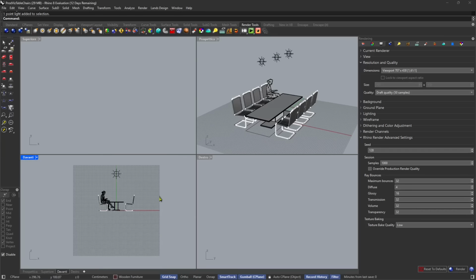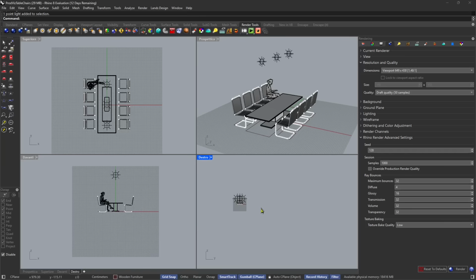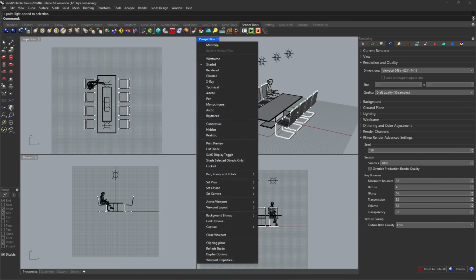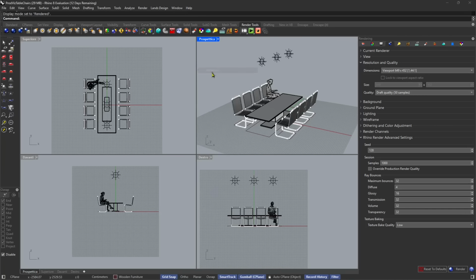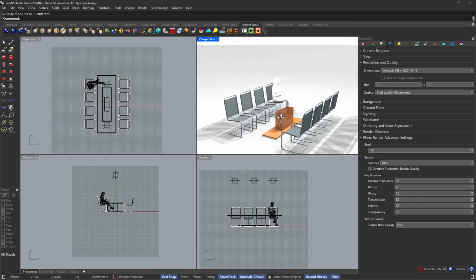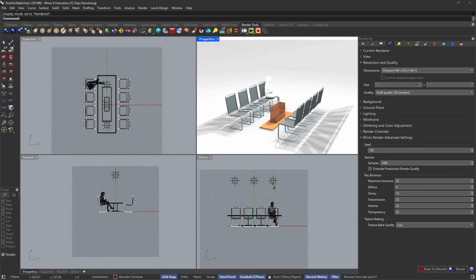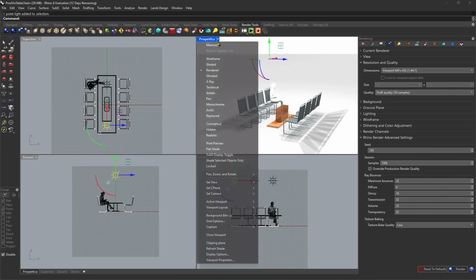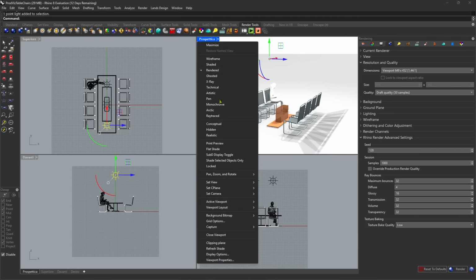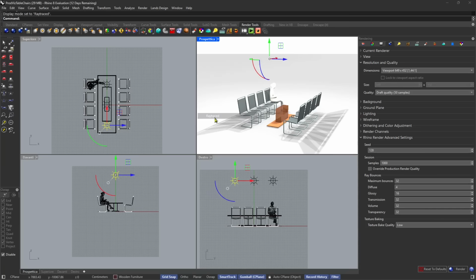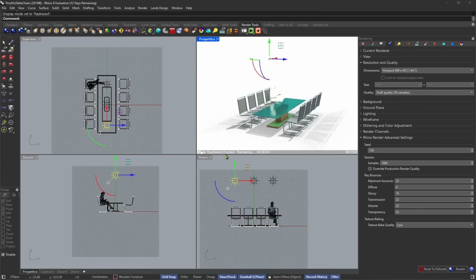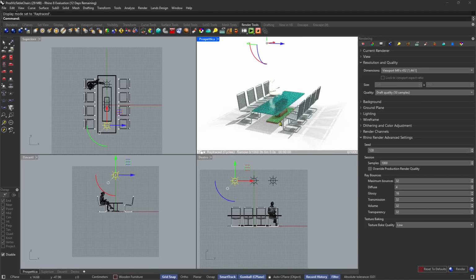So there's nothing in here. I didn't set up anything. So if I run a render, let's see what's going to happen. I'm going to select the view that I want, and I'm just going to switch to the basic render, and this is what we're going to see, which is the light coming from those 3 lights up there. The materials are not so good, and everything is kind of fake. But this is the basic render view in Rhino. If we go to Raytraced, we will start to use Cycles. We can see it down here, and it gets just a little bit better.